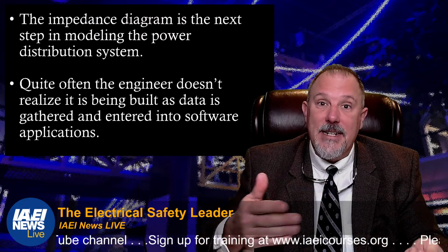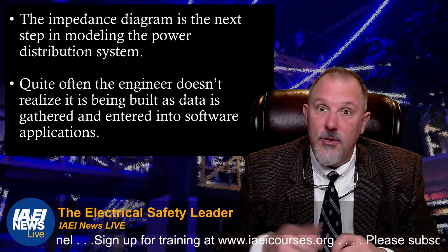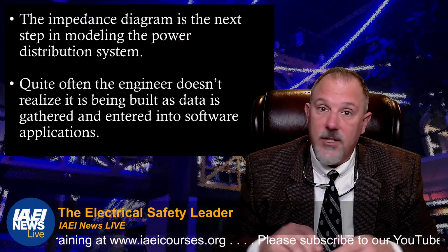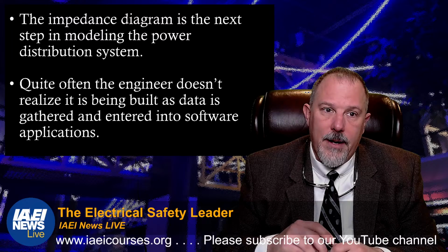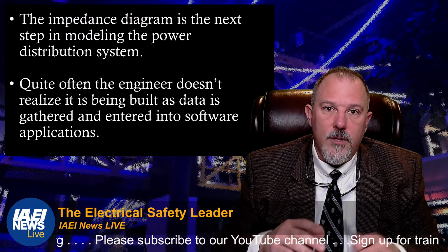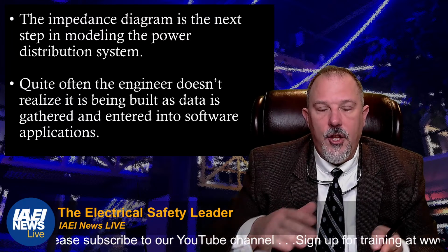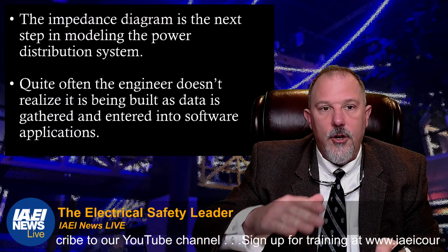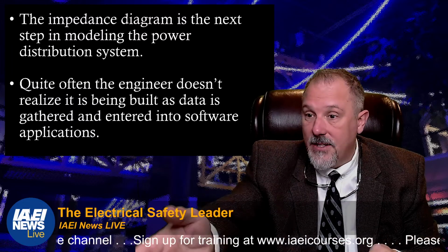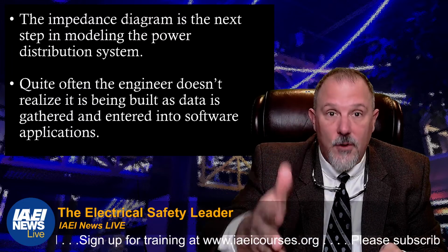I know I did two short circuit studies by hand, large systems, just to learn. That's what my mentor had me do. You will take your one-line diagram and put that into an impedance diagram. Yes, another important role is your voltage drop.